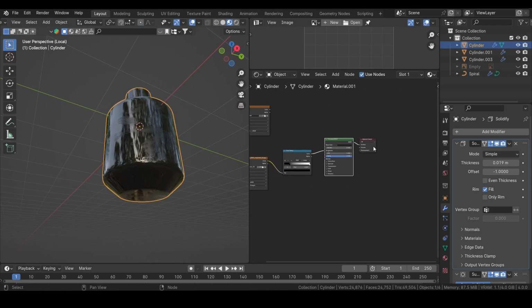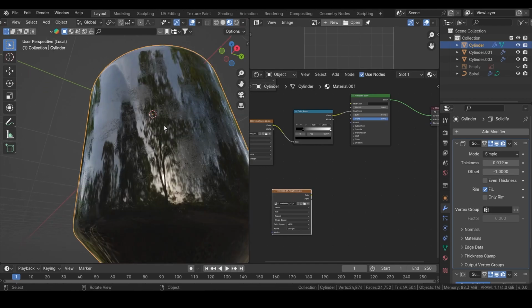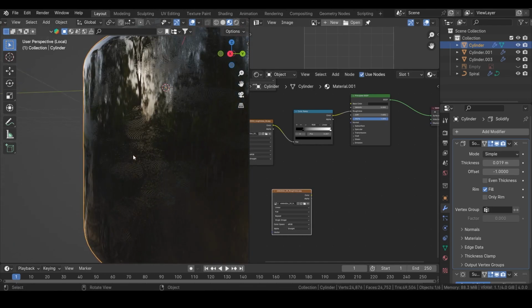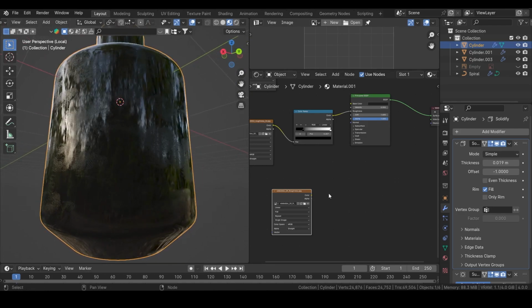The next thing we need to do is to add scratches. Same thing with the scratches, but for scratches, and I learned this recently, you should add scratches to a displacement channel, because scratches are surface detail. While fingerprints don't necessarily have surface detail, they're just like an image on the bottle when you hold an object, scratches generate deformations on the surface, so it should be on the displacement map.